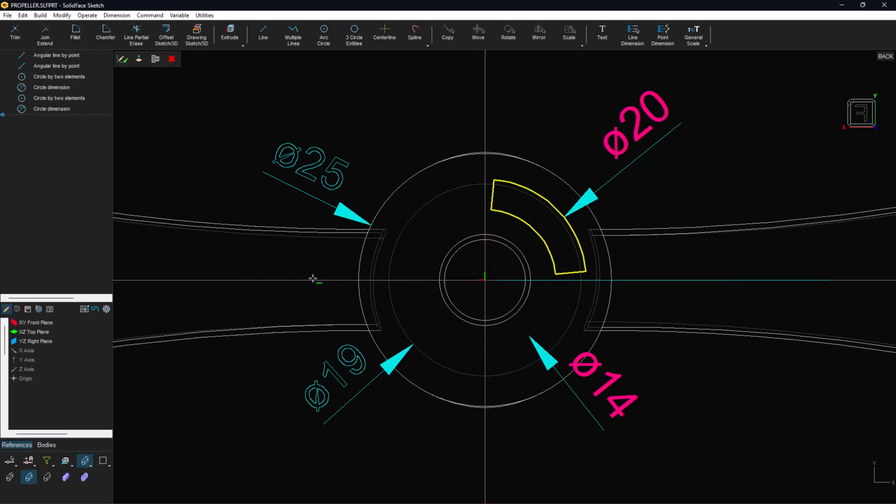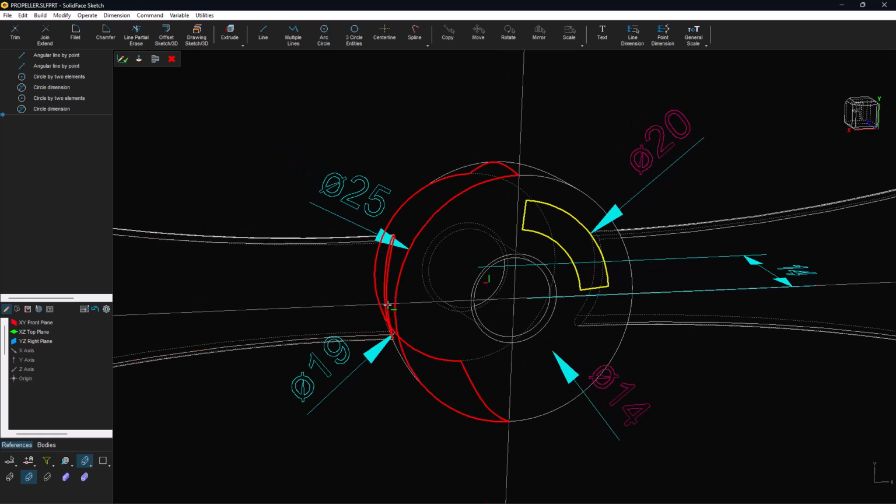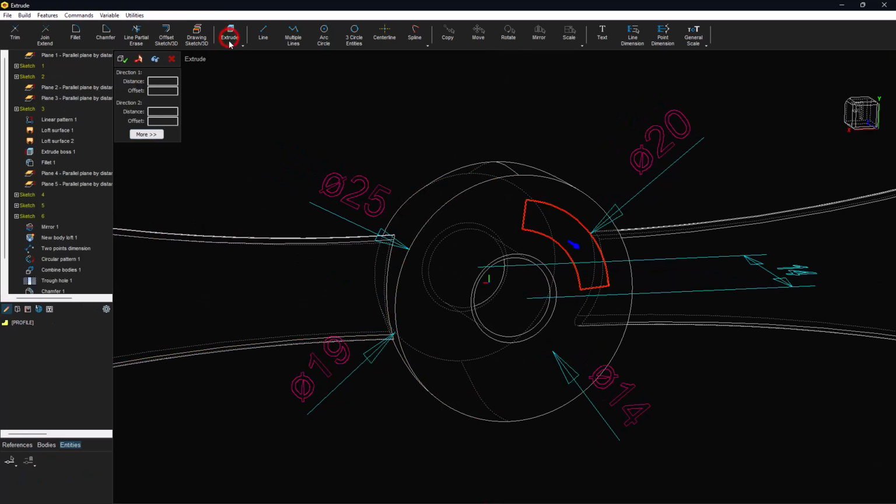At this point, the 3 more contours can be created by multiplying the first contour by rotation in the sketch environment, and then creating an extrusion by cutting all contours in one single operation. Or first use the extrusion feature with the first contour, and then in the 3D environment, use the rotation pattern to create the other cut operations. Choose the last option, create the contour extrusion operation.